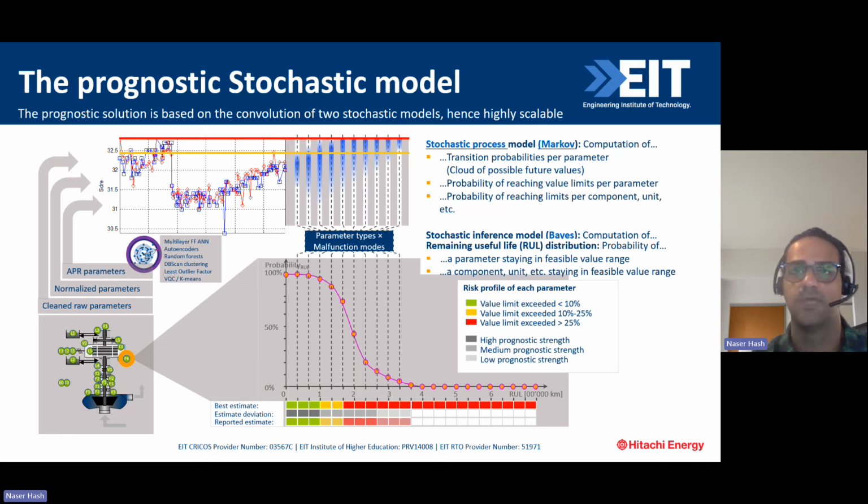So the data comes up to today, and then the Markov chain trends that data based on the history of the variation in the data. And after that, we can use the Bayesian rules. Bayesian rules are based on calculating the probability of failure. So we have different types of data coming in for detecting a failure mode, for example, the insulation degradation or short circuit for the winding of the generator. We need the temperature on the three phases, we need the current, and also we need, for example, the ambient temperature. So these are the minimum three sets of data which come to the Markov chain.